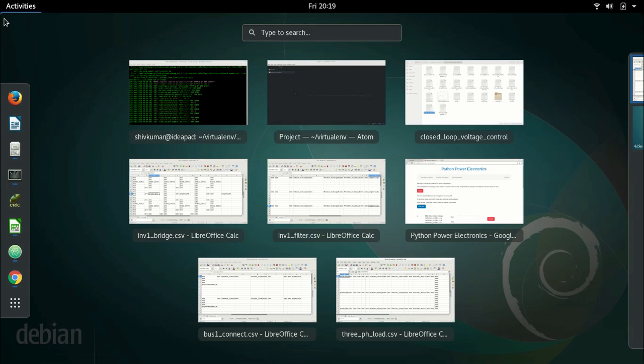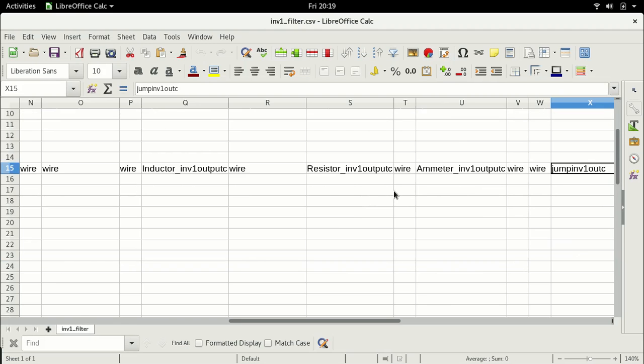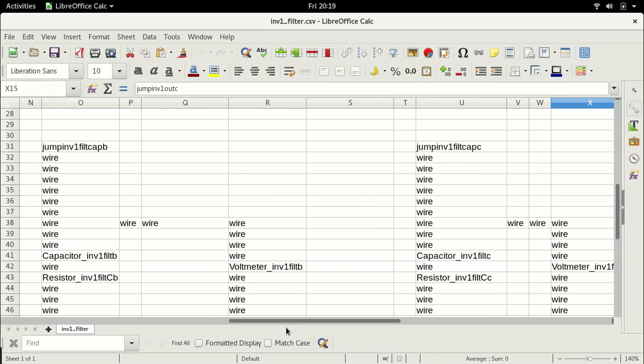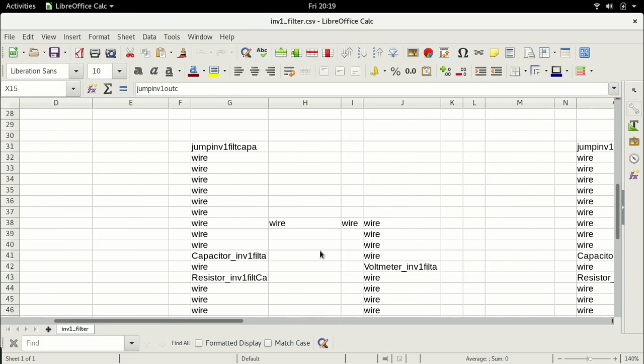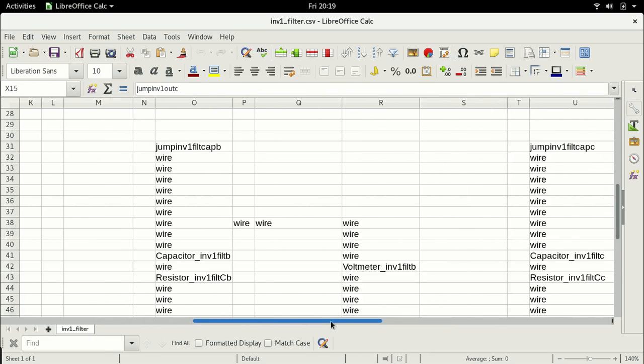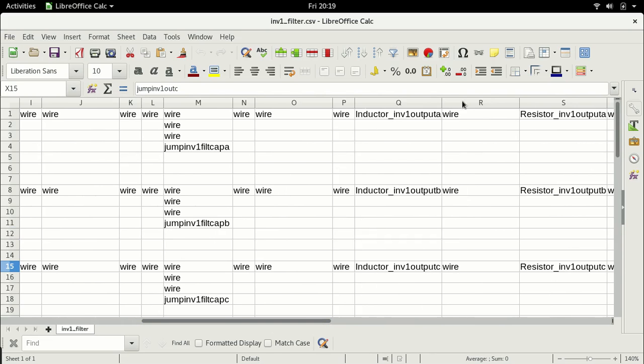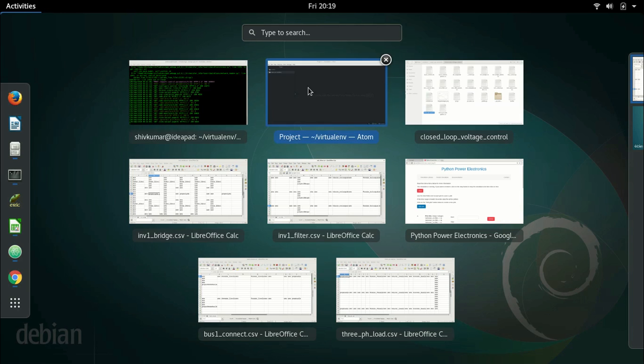So now that we have shown you this, what exactly are we trying to do? What we are trying to do is regulate the voltage across these filter capacitors. If we regulate the voltage across these filter capacitors, we are essentially regulating the output of the UPS, because this is the output. Everything that comes to the right of this bank is the output of the UPS. So if we regulate the voltage across these three nodes, we are regulating the voltage that is fed to any load. Alright, so let's go back and let's look at our control files now.